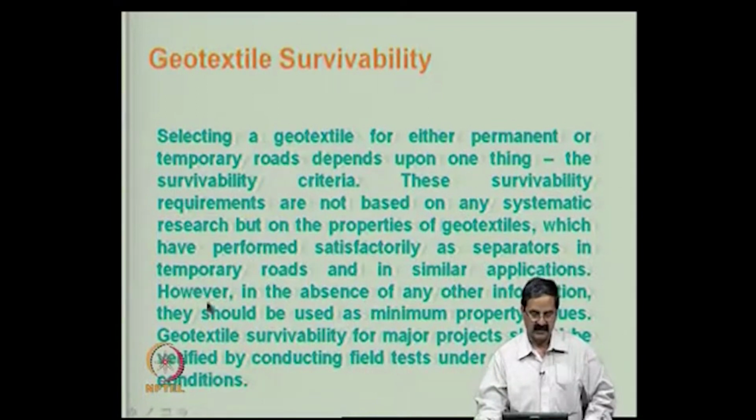So the geotextiles and their survivability is already given in some standard, in the manufacturing literature. If you buy a geotextile of a particular grade, they will clearly give you the apparent opening size. If you want to take the permeability criteria also in pavement design, apparent opening size is required, and if a reinforcement function is required, its stiffness is required.